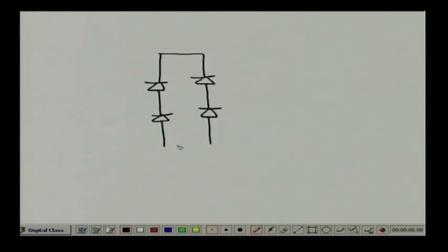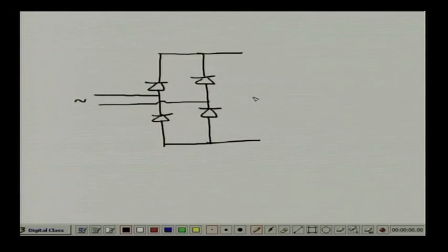In other applications, as you know, we usually make our power supply. So, typically a power supply looks like this, all instruments need the power supply. Right. So, I am giving a supply here, right. This is our AC supply. After stepping down and all, this is a full wave rectifier. So, I am getting a DC here, positive this side, negative this side, this is AC this side.